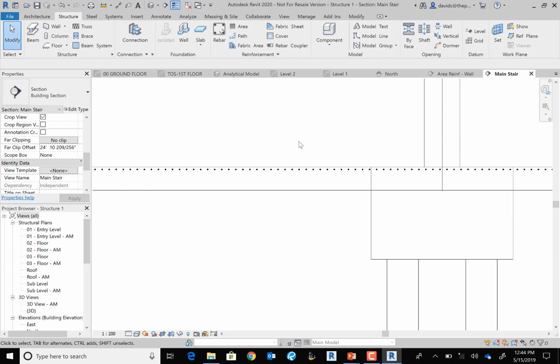If you have hollow core slabs, it'll actually bring in a hollow core family and place the entire thing throughout your entire floor. It'll adjust the panels to size, and then it creates an assembly out of the elements that it precasts or makes, right? Then it generates those onto sheets, and it will place all of those onto sheets with a typical parts list. They're all annotated, and there's a material takeoff there for you.